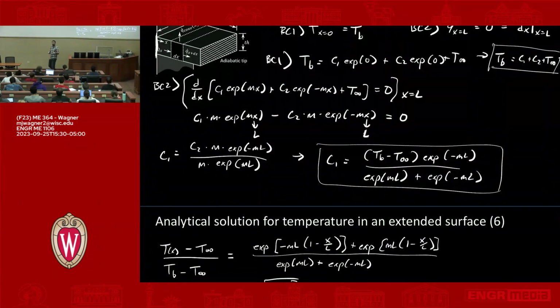In the homework, as you'll see, I've added a little bit more complexity. I guess I'm kind of mean. You have convection to worry about, and you also have radiation. So you're going to have an M that involves both convection and radiation. Importantly for the homework, if you try to solve for the radiation part and include temperature as a variable, you're not going to be able to solve it.